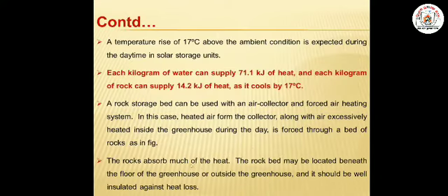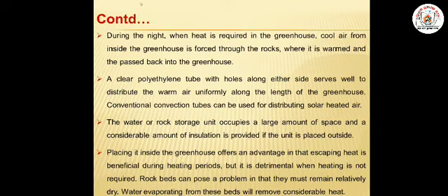The rocks absorb much of the heat. The rock bed may be located beneath the floor of the greenhouse or outside the greenhouse, and it should be well insulated against heat loss. During the night, when heat is required in the greenhouse, cool air from inside the greenhouse is forced through the rocks, where it is warmed, and it is passed back into the greenhouse. So in this way, heat exchange from the rock to the cool air takes place in the rock bed.